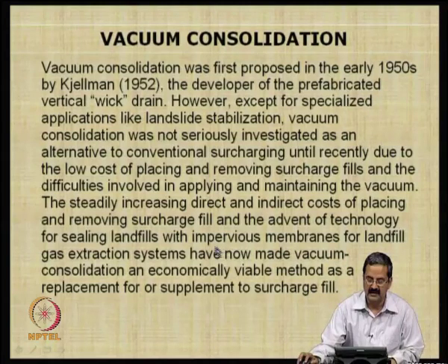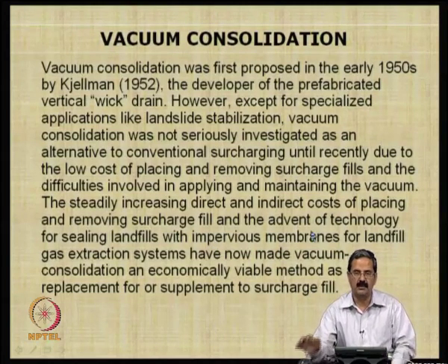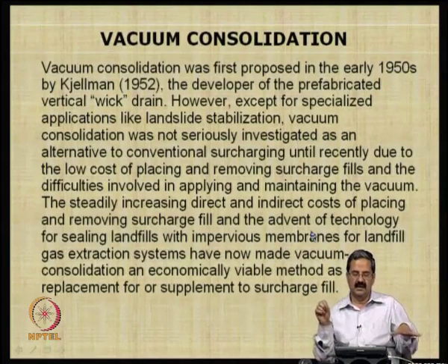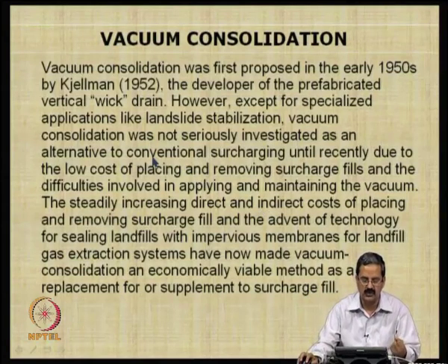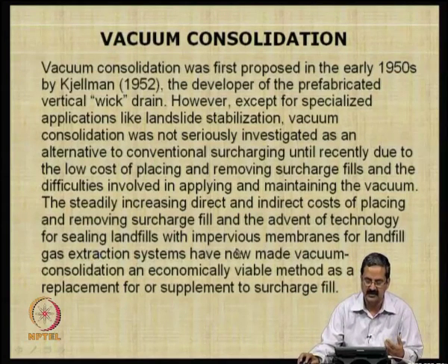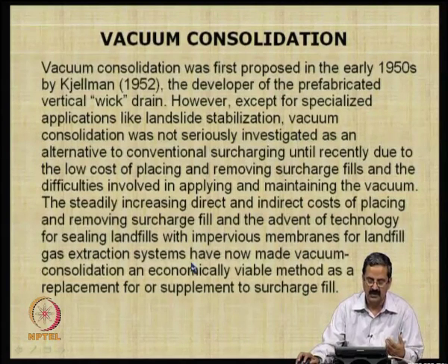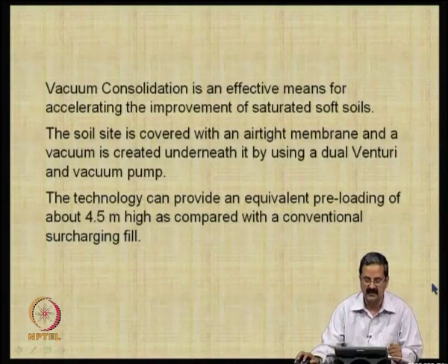People have to use geomembranes in landfills, and you create some vacuum, using some vacuum technology for sealing. With the advent of technology for sealing landfills with impervious membranes for landfill gas extraction systems, the technology has improved so much that it has become more economical and viable as a replacement or supplement for surcharge fill.